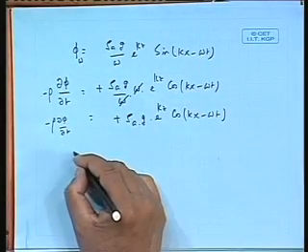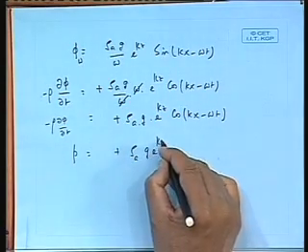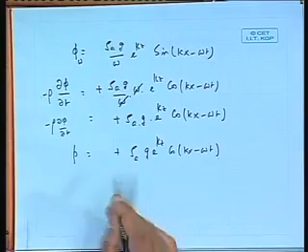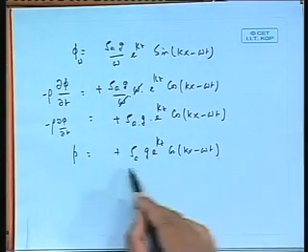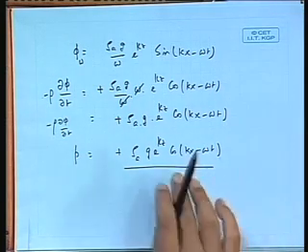So I end up getting this part of the pressure as plus rho xi a g e to the power kz cos of kx minus omega t. This is my linear dynamic pressure, that is the d phi by dt part. Of course we also have the rho g z part. Now again you can see this is sinusoidal. It's a cos curve. Again it varies with time in a sine form. But there is a very important concept associated with pressure. This I would like to talk to you about a little bit now. Let me take a very high wave like that.